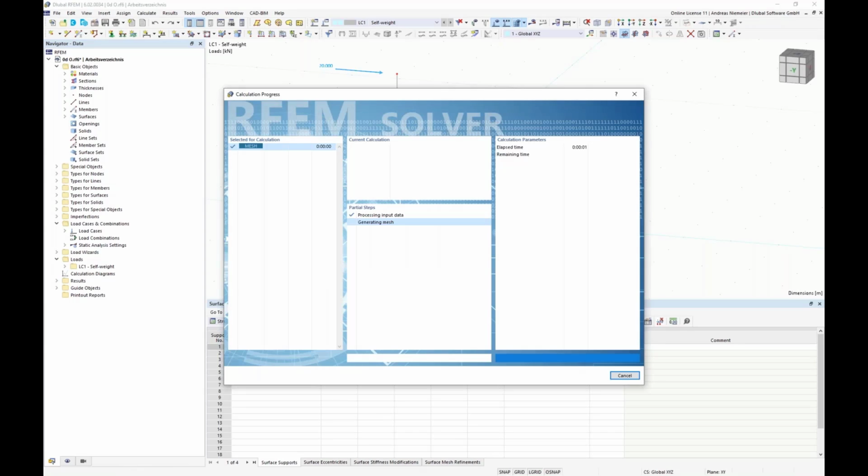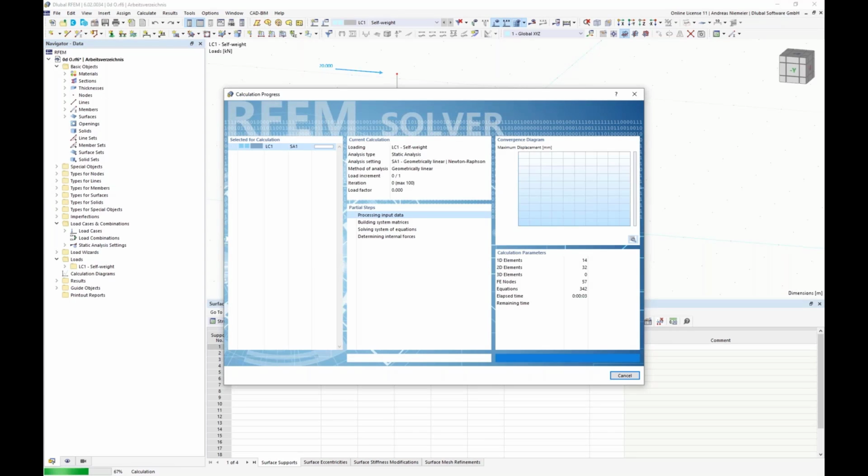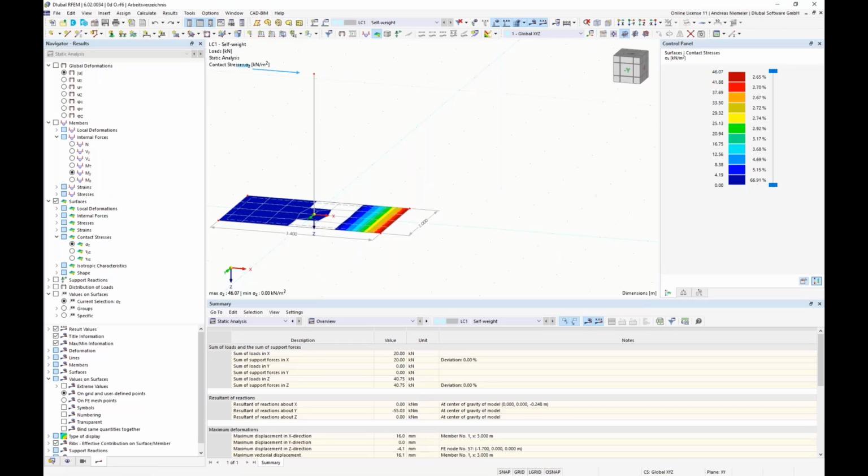This was now a manual optimization, what we did. I think you know it, and I know it also from our support work. When we try to get a model that fits, we play with these parameters, which is quite boring and time-exhausting work. And even if we reach a foundation size of, let's say, 4 tons roundabout, we cannot be sure if this is a good optimization, because we changed only this parameter in X direction. We don't change this parameter in Y direction and the thickness parameter.